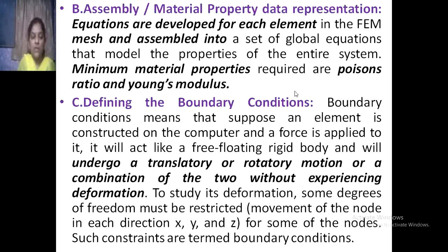So minimum material properties required are Poisson's ratio and Young's modulus. So defining the boundary conditions. Boundary conditions means that suppose an element is constructed on the computer and a force is applied to it.